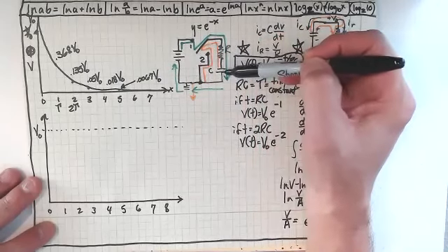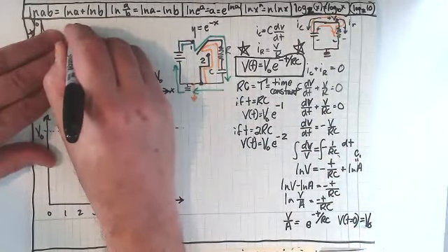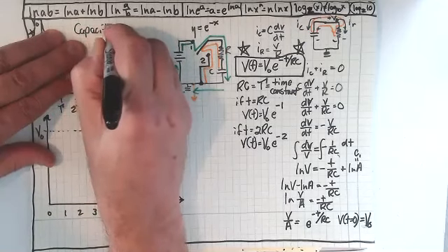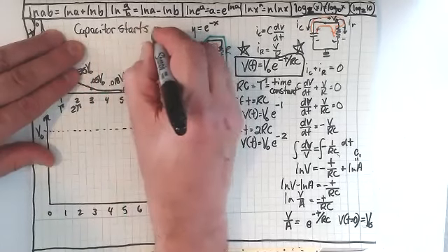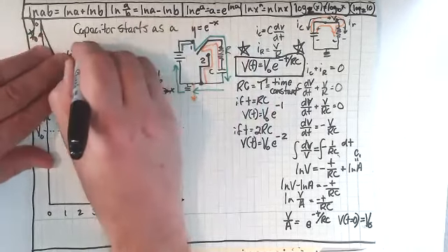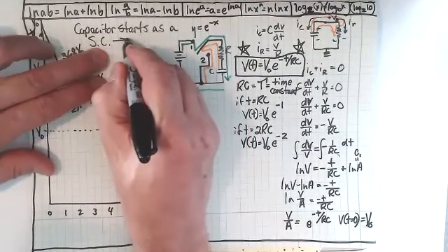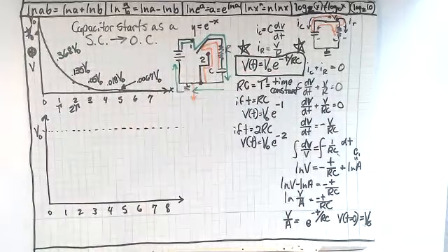So remember, a capacitor starts as a short. Let's write that because it's so important. Capacitor starts as a short circuit and goes to an open circuit, right?